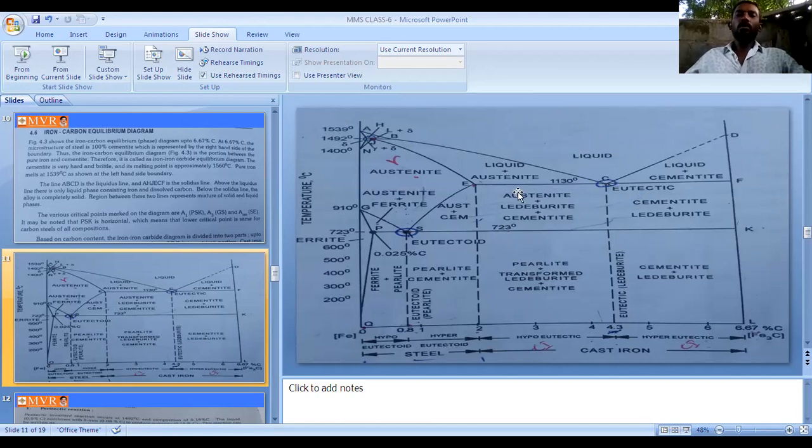So it comes to the cooling one, cooling for steels. Here at cooling, what are we doing? We are cooling the steel. When we cool steel, see, with carbon content 0 to 0.8% we can call it hypoeutectoid steel. 0.8 to 2% we can call hypereutectoid steel. But what is the steel? Carbon content 0 to 2% we can call as the steel.